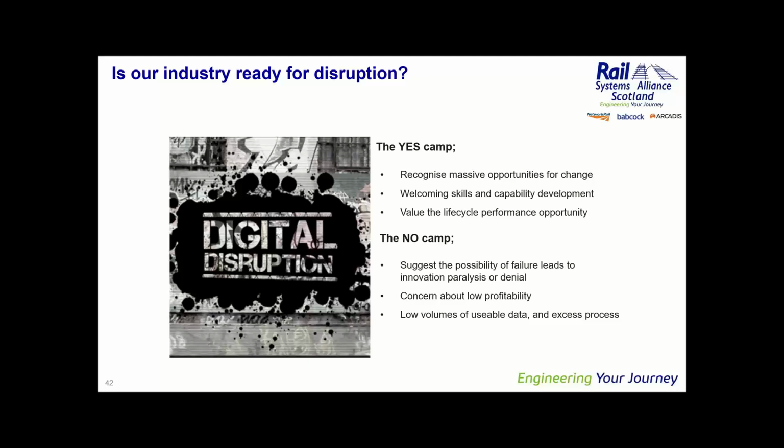But when you talk about a building, for example, I said earlier on in the presentation that public sector clients such as the National Health Service and the Department of Justice have very, very well defined information agreements. They specify the information that they want out of their model so that they end up with a digital facilities management model. The digital facilities management model gives them advance notice of when they expect aspects of the building to reach the end of life, and so they can program their maintenance from the digital model.